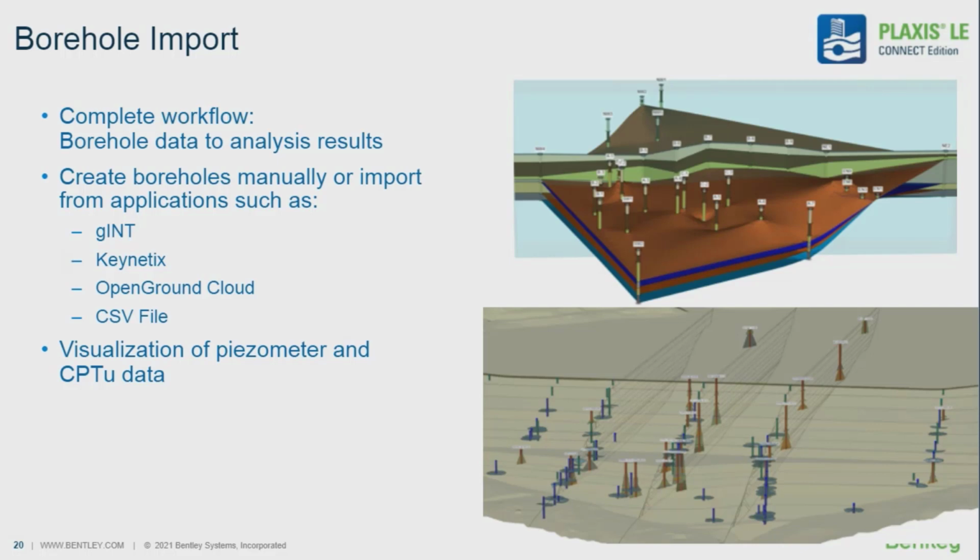Besides this, we also can visualize the piezometers and CPTU data in PLAXIS Designer. Okay, you can see here a complex but extremely realistic example of a tailings dam, and you see the position of these instruments along each of these cross-section planes here, and also the measurements regarding each of the equipments, so we can interpolate and also generate the surface, the water table representation between those readings.